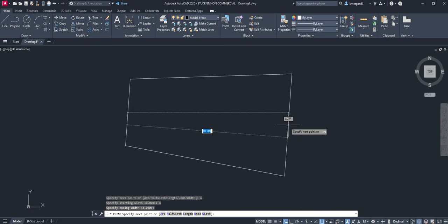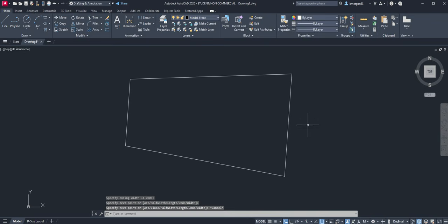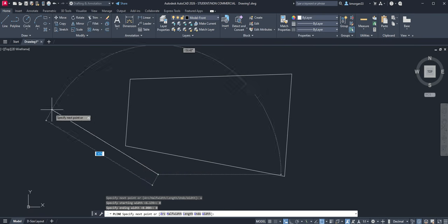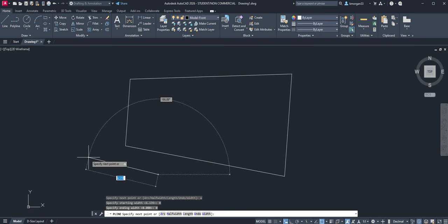In order for you to fix that, you have to go back to the polyline. Then of course you click on the canvas to give it a point, and then go back to W, enter, 0, enter, 0, enter. That will get you back to the regular polyline. I see many students, because we of course show you how to make it.